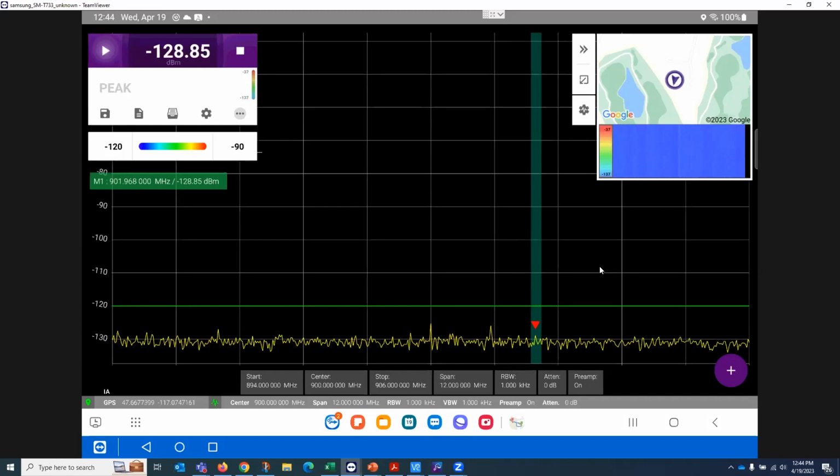And in the world of LTE, which is what we're talking mostly about here in FDD, each one of those resource blocks, or that width of the spectrum, is roughly 180 kilohertz wide. Actually, I think it's exactly 180 kilohertz wide for your PRBs, and there are so many of them. So, say AT&T, Verizon, T-Mobile tell the end user, hey, it's PRB 33 or PRB 14. We tune to that one, and then we adjust the width to whatever we want, right?